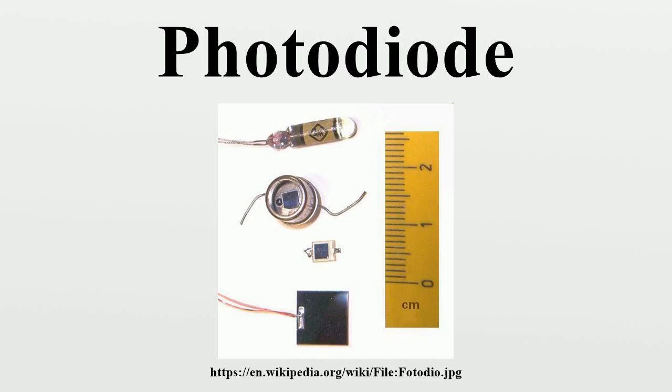Photodiodes are often used for accurate measurement of light intensity in science and industry. They generally have a more linear response than photoconductors. They are also widely used in various medical applications, such as detectors for computed tomography, instruments to analyze samples, and pulse oximeters. PIN diodes are much faster and more sensitive than PN junction diodes, and hence are often used for optical communications and in lighting regulation.